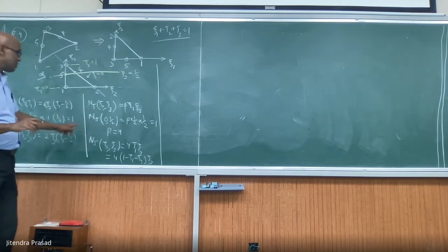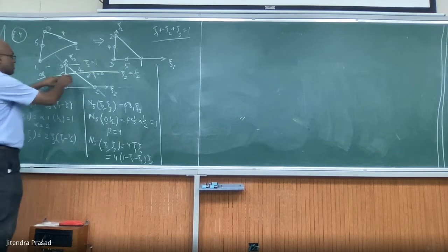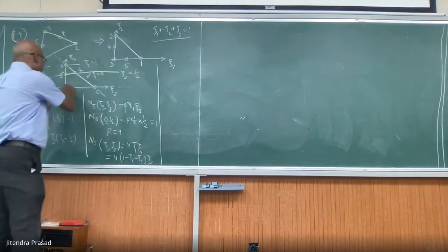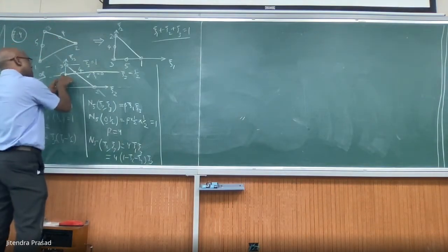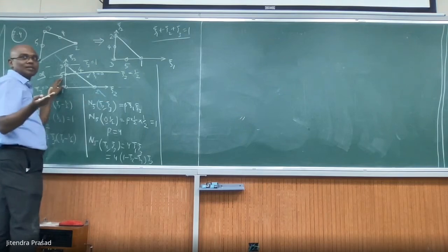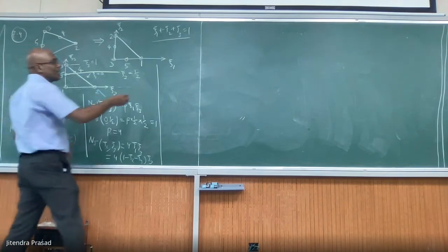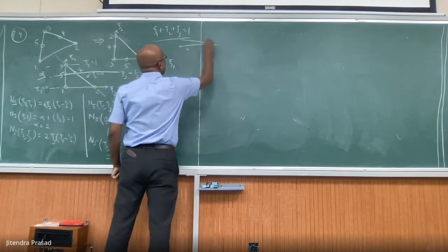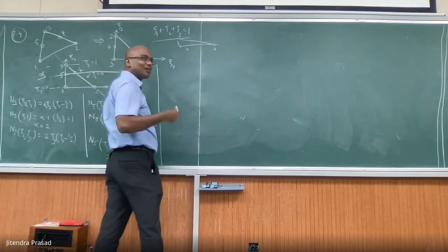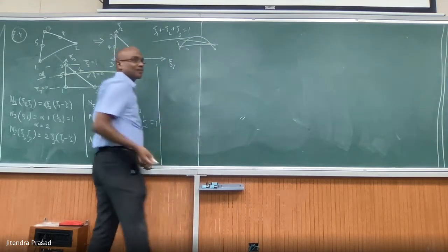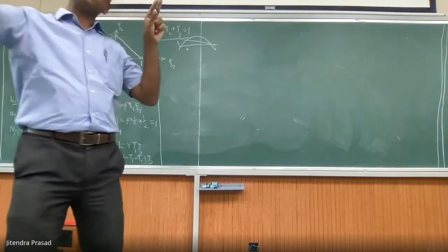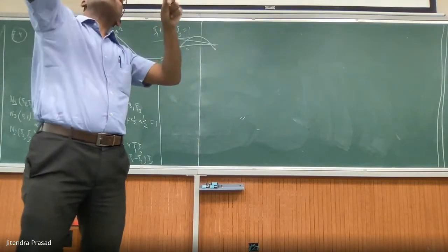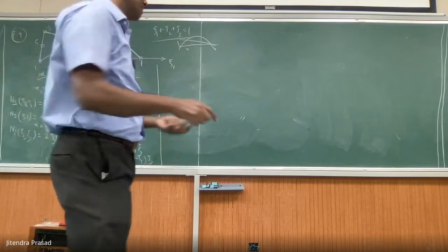N5, if you see what happens, N5 is linear. If you go here, the value will be something like this: 1 here going to 0 linearly, and that's what is meant. Linear here will be either 0 to 0 linear, or 1 to 0 linear. So linear only. It should not go like this. That's the only thing. So a 0 0 value, a line only. 1 0 value, line only. It should not be 0 0 here with some value in the middle. In that case, it becomes quadratic.